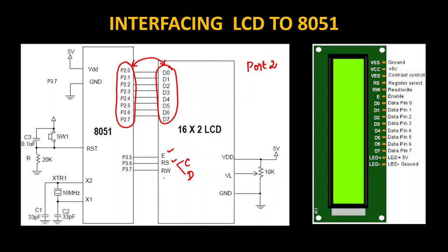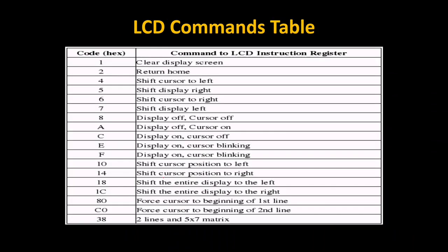So read write is going to determine whether it is going to read the data or write the data inside your LCD. So these are the things which are going to be used for our programming. So these pins we have to make sure that correspondingly we will activate those pins to do the job at that specific point of time, right?